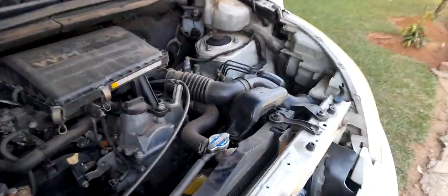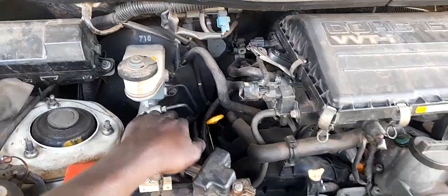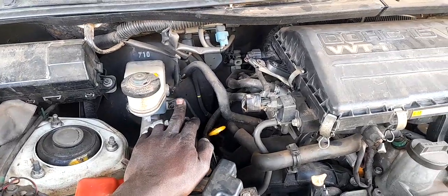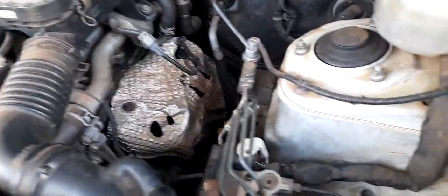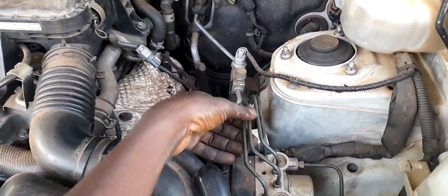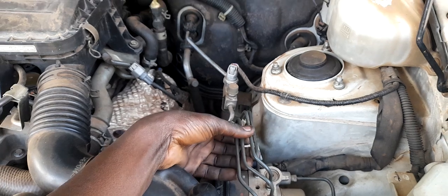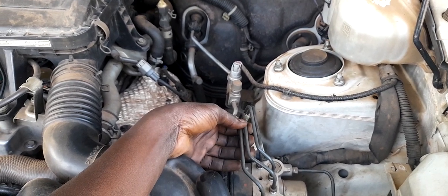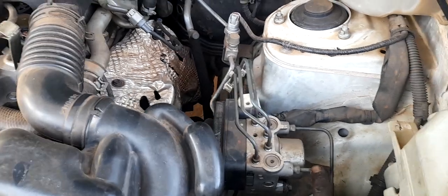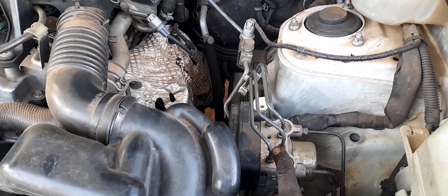When you bypass the motor, this brake fluid coming from here will go just directly to the wheels. It will not pass through here in the ABS module. Now during bypass, you will need like 2 T-junctions. We call them T-junctions. This fluid will come from here, it will enter here.